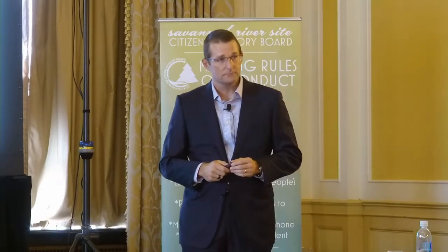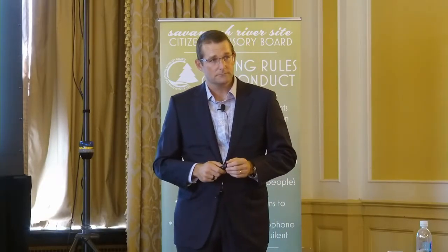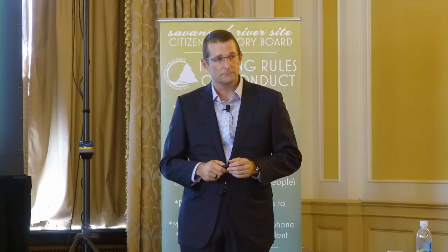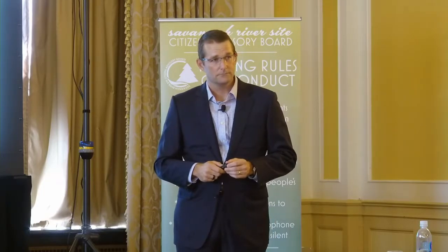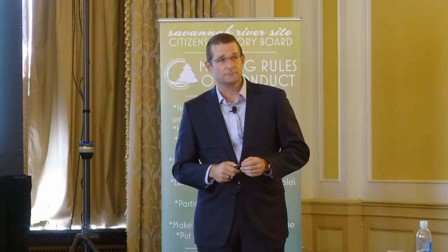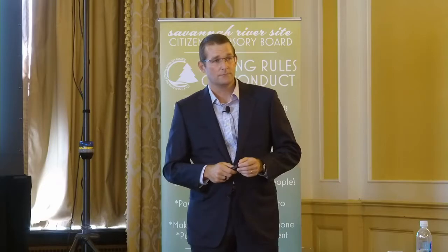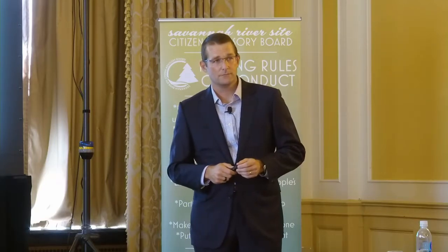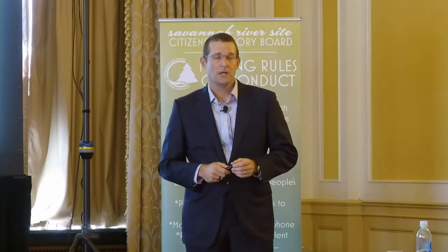Bob Smith, CAB. I'm assuming that your foreign materials that are included have a slightly different, or if not significant different density than your solution, your salt solution. Yes, that is correct. They're heavier. Have you thought about using a hydroclone or a strainer in front of the pumps to catch the foreign material?